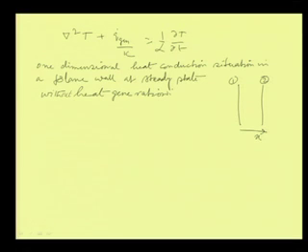So, what happens? Now, our basic equation is this, del square T plus q dot generation by k is equal to 1 by alpha del T by del t. Now, it is told that it is steady state. So, once it is steady state, this term goes 0.